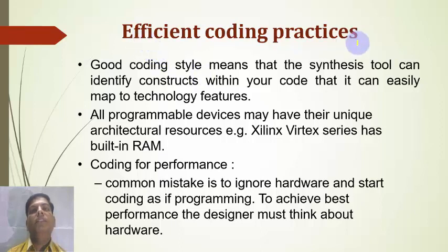Efficient coding practices. Good coding style means that the synthesis tool can identify the constructs within your code that it can easily map to the technology features. All programmable devices may have their unique architectural resources. Example, the Xilinx Virtex series has built-in RAM.